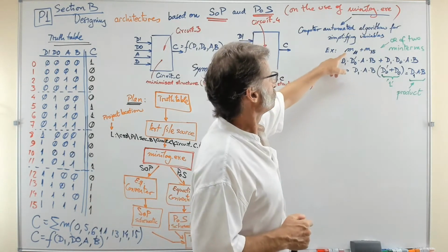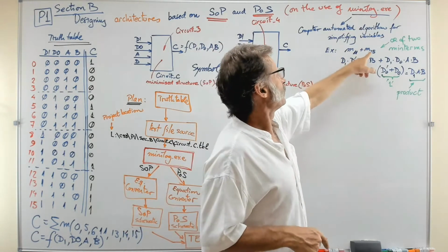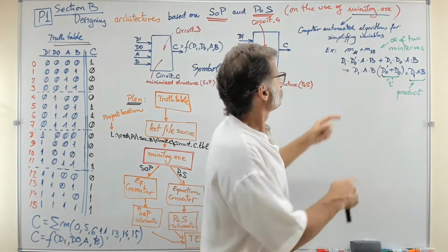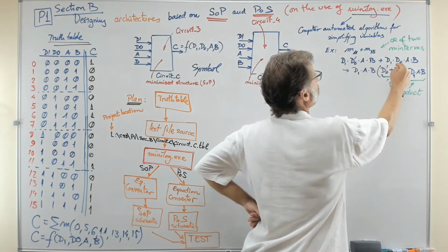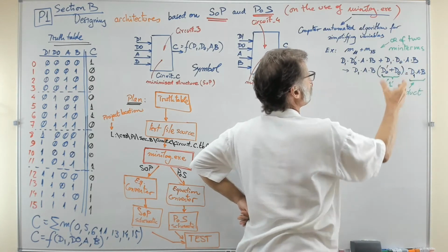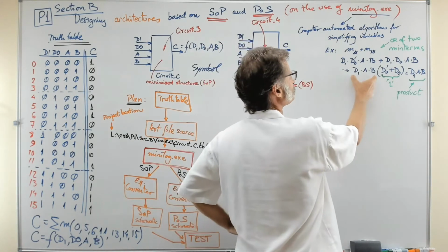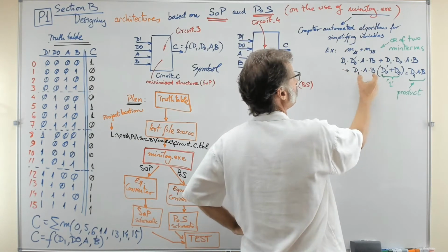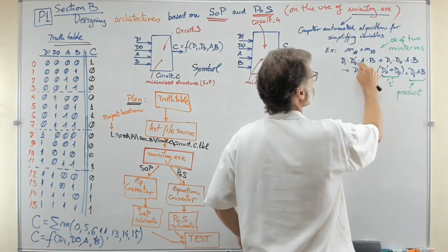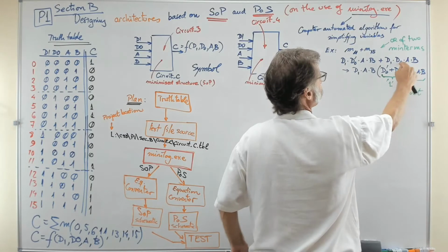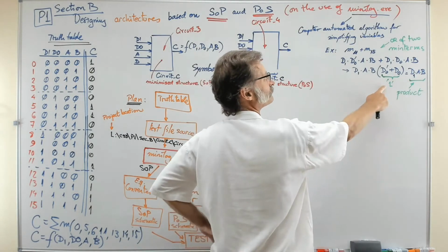You can imagine that the C is the sum of two minterms. And this means that you've got this term, D1, D0 naught, A and B, or D1, D0, A, B. So if you have this OR, you know that you can extract here a common factor, D1, A, B, and then you can place in brackets D0 naught or D0, and you know that this is simply a 1.